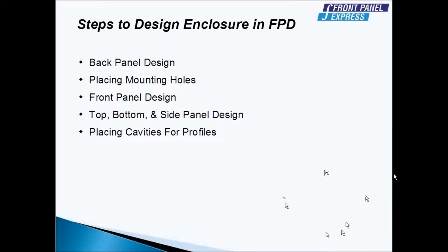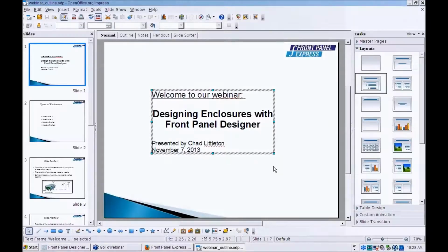Also, we have a question regarding the housing brackets. Now, this is in our enclosure manual, and this will have a dimension off the top and bottom of how the distance between the front panel and the edge of the part to associate to get the same distance and support and have extra strength. This is also placed at your discretion on how supportive you need this, so you can space them out. We recommend a minimum of 100 millimeters if it's a really large enclosure.